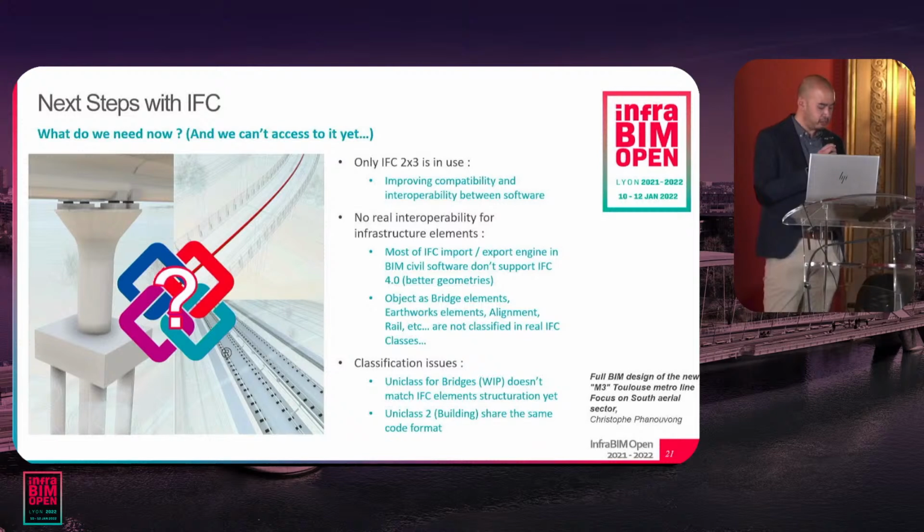We wanted to use IFC 4.0 at the minimum, as asked at the beginning of the project, but we noticed that some software like ArchiCAD or Civil 3D have an import-export engine, the IFC engine inside this software, that is not very satisfying for all the different exchanges that we have. We wanted to have better geometries, and I wanted to avoid some triangulations on the different elements of the project.